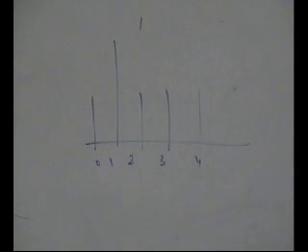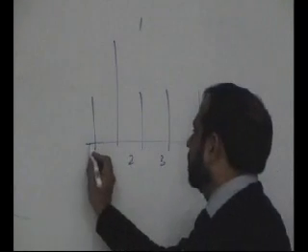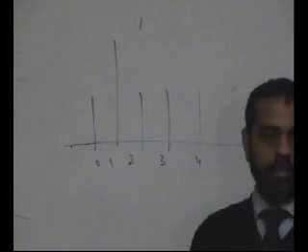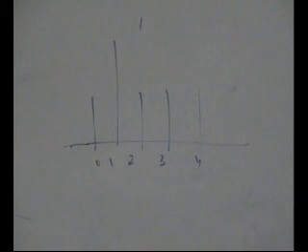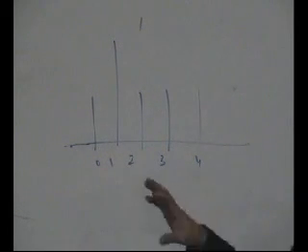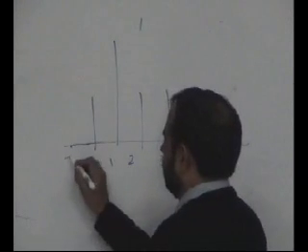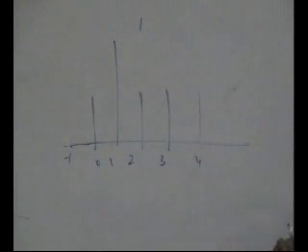Usually the first sample is a corrupt sample. Why? Because there is no signal here. In signal processing, the first few samples will be corrupt samples, and the last few samples will also be corrupt, because you are not really applying, because there is nothing here. You don't know what is there at minus 1. So usually we throw the sample away.